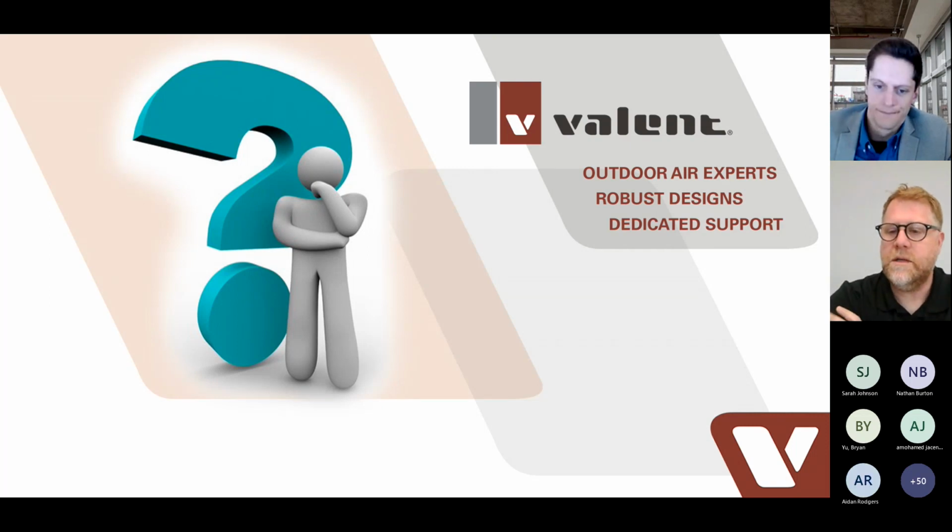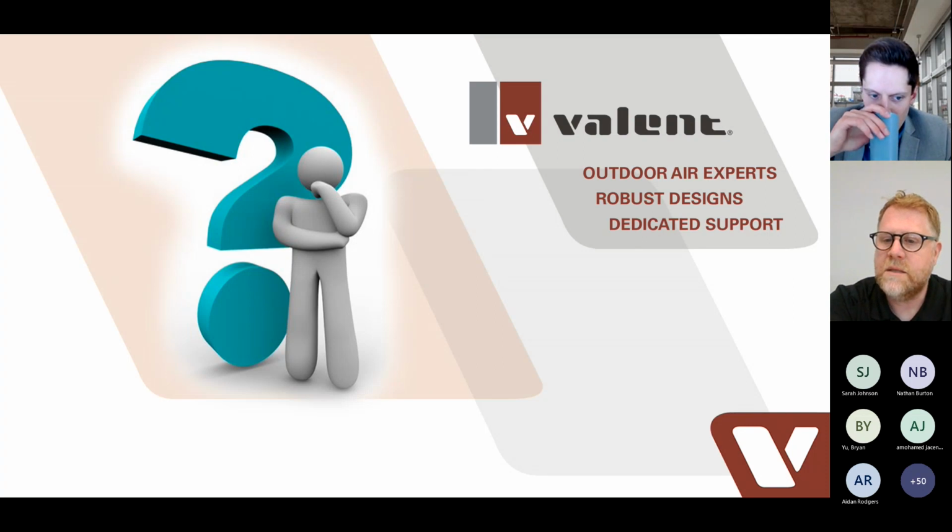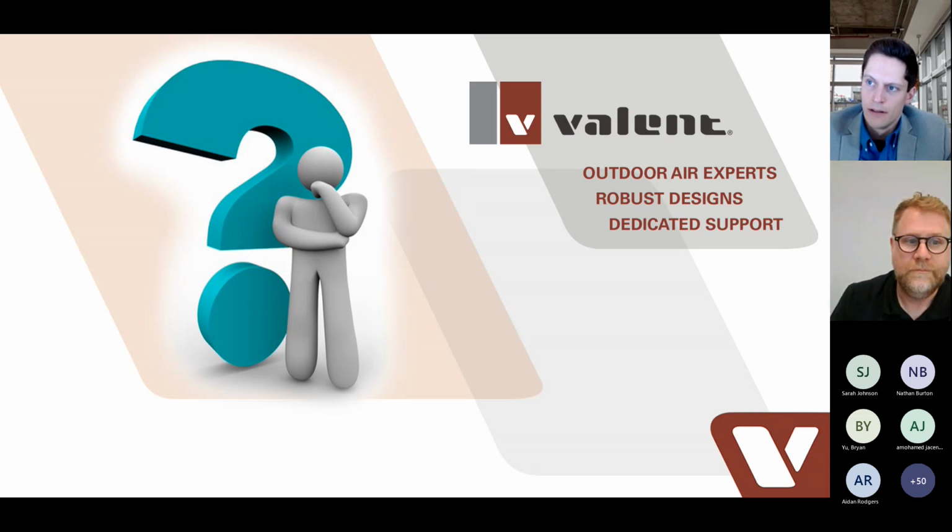Thanks, Brian. Another question came in. What is the best practice to control the DOAS unit used with a terminal unit of the VRF system? Great question. We're seeing a lot more of this, especially as VRF keeps rolling along. I don't know if there's a best answer. There's rarely a best answer for anything that applies to all situations, but I would say the most common one that I see is duct static pressure control. That's how you control your supply fan.